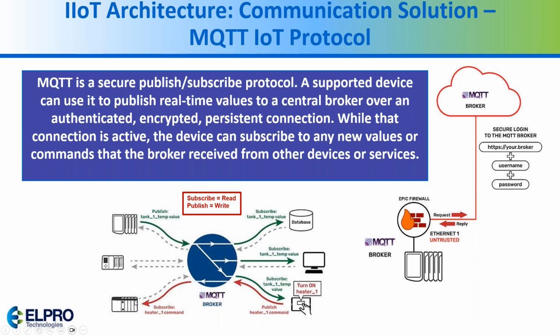What I'm going to show is our radios are going to be writing the information to a local broker in this area, and then also to one in the cloud. And then I'm going to show VT SCADA and Ignition acting as clients to read the information and display it.